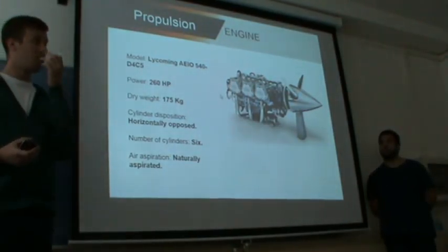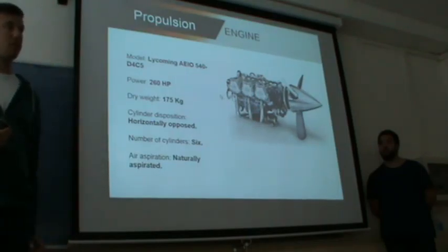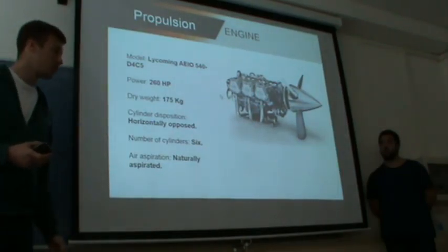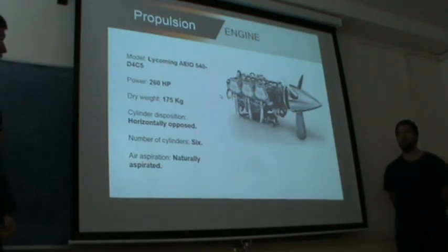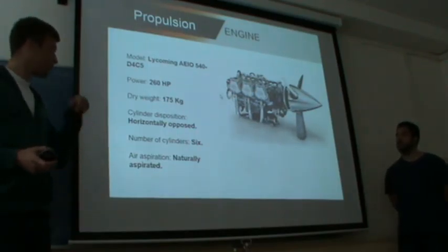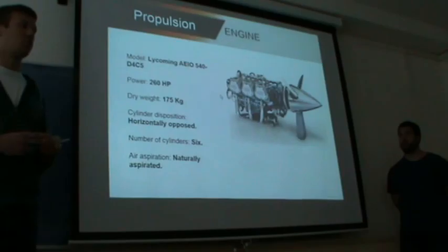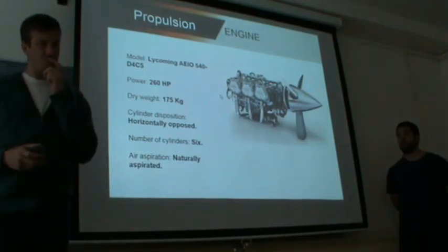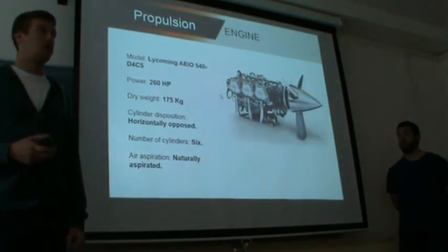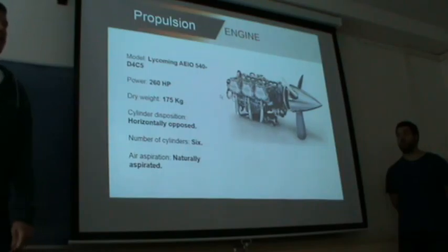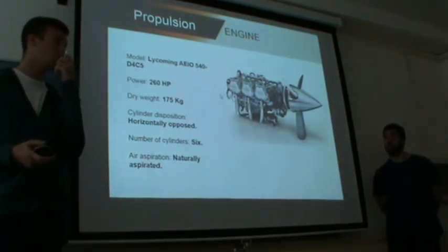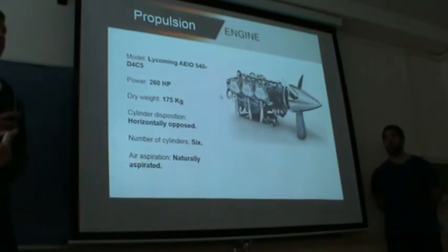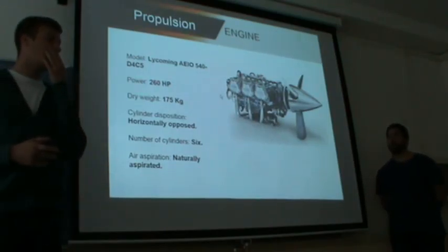The manifold pressure is the same as the atmospheric pressure because we haven't installed any compressors; there is no turbocharger or supercharger. And just to finish, I'll say that the propulsion department is working on the variable pitch propeller selection, which includes spinner, governor, hub, and the blades.